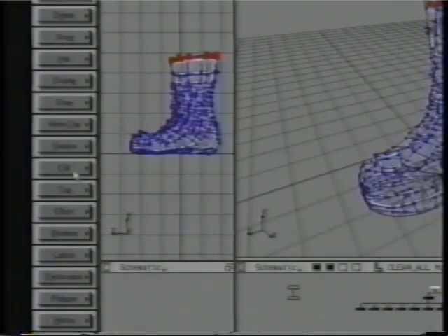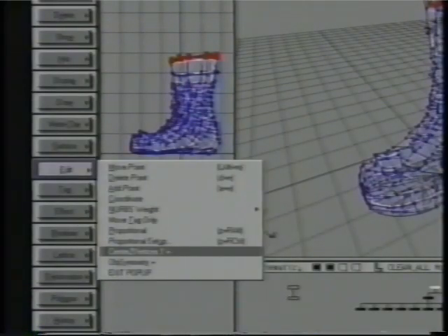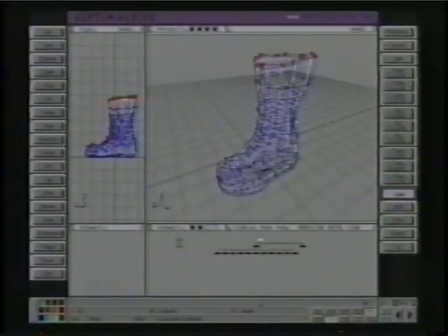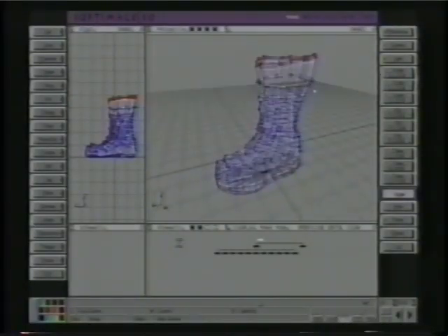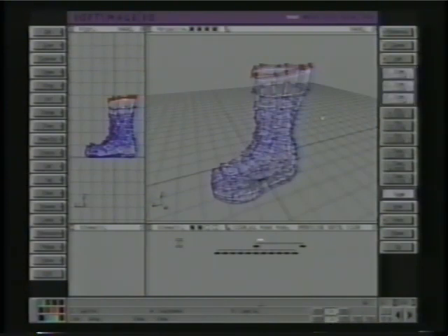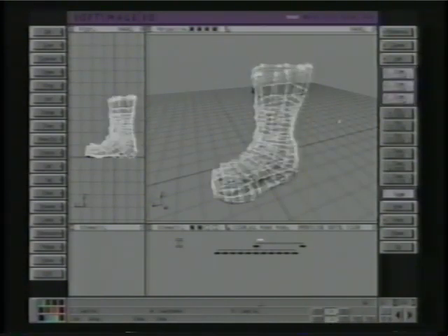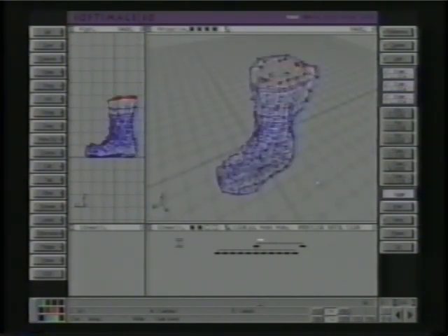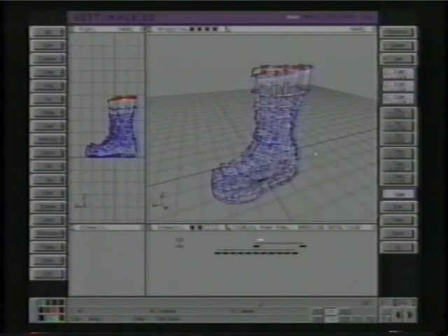But it's a whole lot easier. Just come over here, edit centered vertices. Now the center has jumped to right in the middle between all those points. If you don't have any points selected, then it'll go to the middle of the object. But with them selected, do it again, you can then do things like scale towards the center. So this I use constantly in modeling to do things like scale and rotate around a certain point.